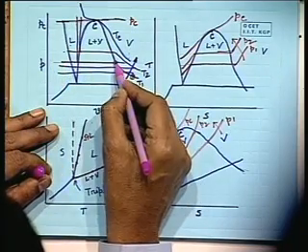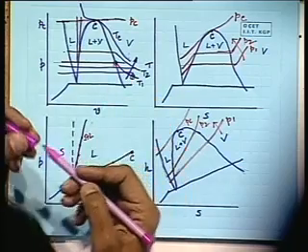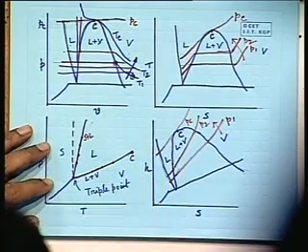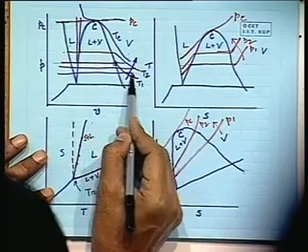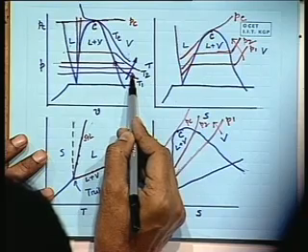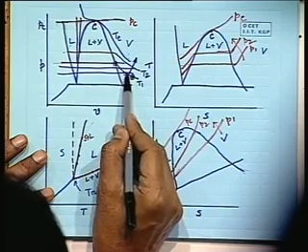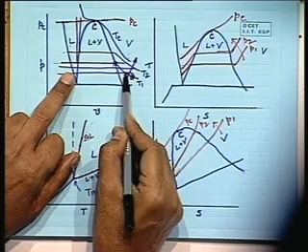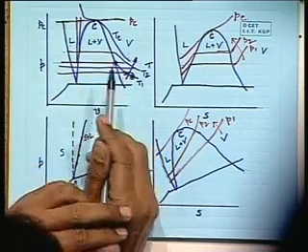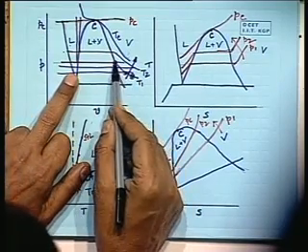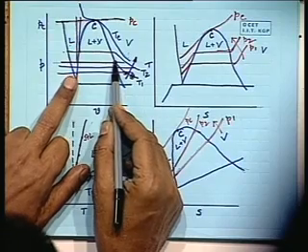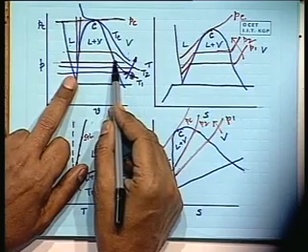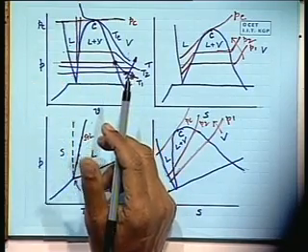So this temperature is 100 degrees Celsius. So this is the saturation temperature. Now if this 100 degrees Celsius line extends here and you are at some point here, for example here, whose pressure is lower than the 1 atmospheric pressure, that means it is in vapor state. That means if you compress that vapor to 1 atmospheric pressure, then only it will become liquid, because 100 degrees Celsius water at subatmospheric pressure is a vapor.